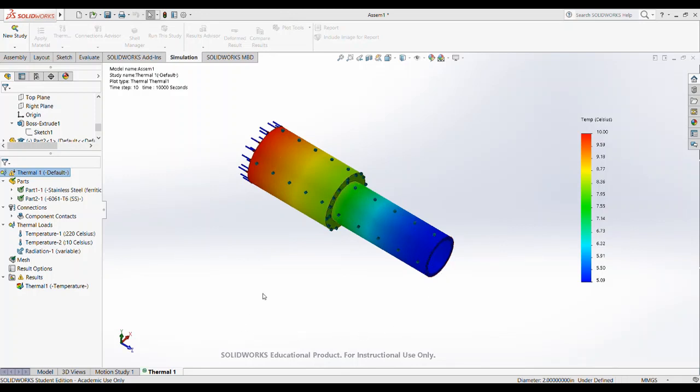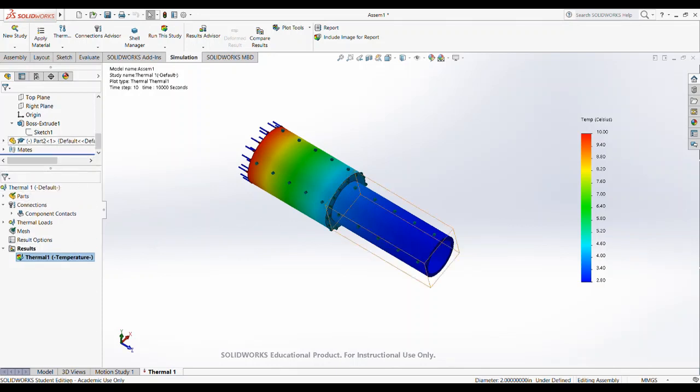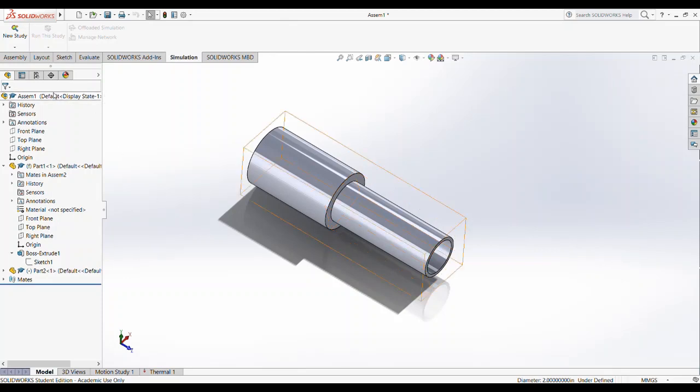Oh, the other thing is I'm not sure I have the right mass. I forgot what the mass was off the top of my head. I'll show you how to measure mass on this thing. So let's go ahead and do the measurement of mass. For that we'll go to click model at the bottom, and go to the SolidWorks menu here. You go to tools, and you can say evaluate and mass properties.